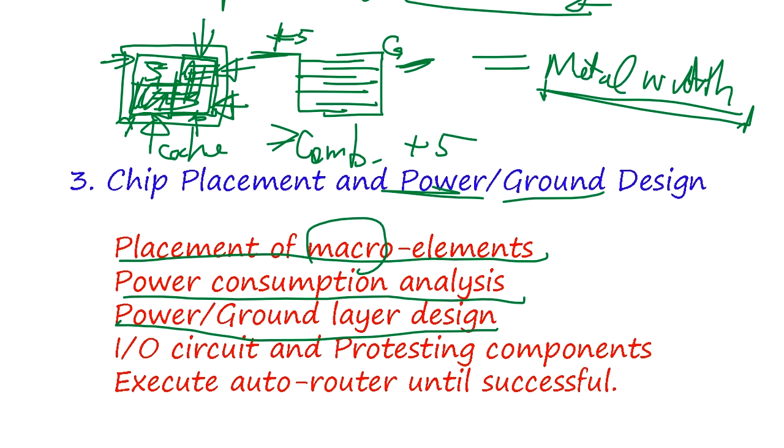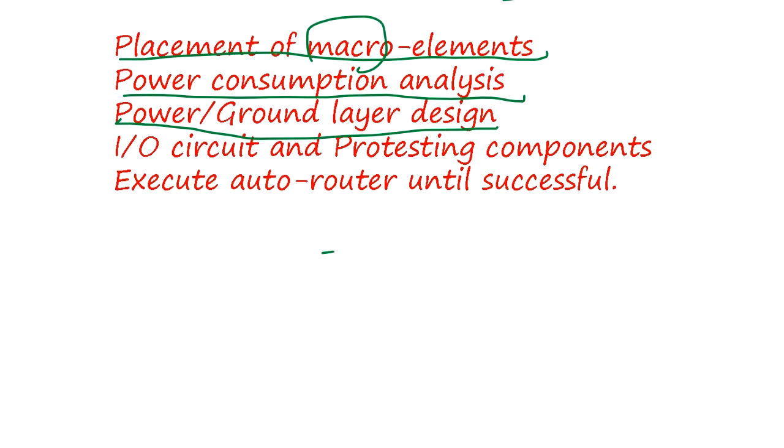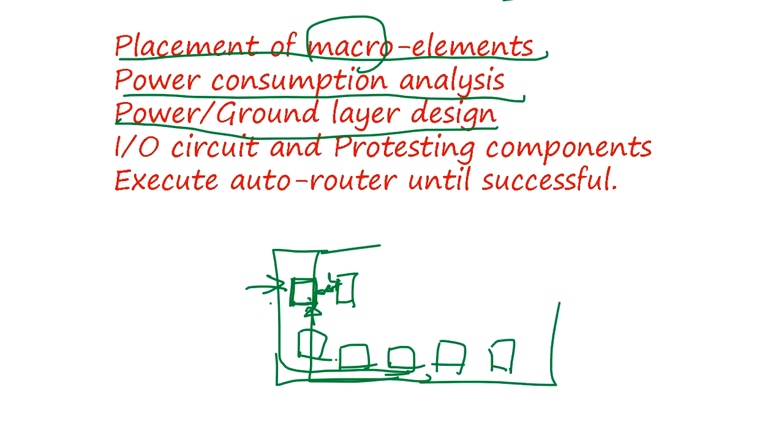And you also have I/O circuits. So what happens is, the I/O circuit is placed, and output logic has a large transistor to provide enough fan out to go out. And I/O typically has bonding pads, and the bonding pads have a reverse diode protection for static damage, and that kind of detail has to be placed. So bonding pads around, and typically those are done manually, depending on the size of the LSI chip.